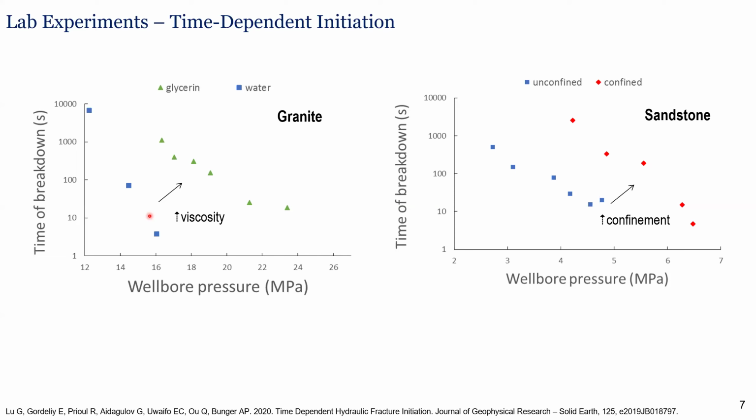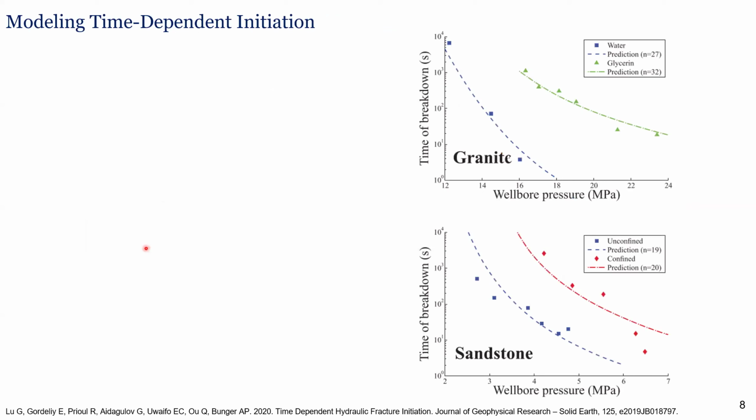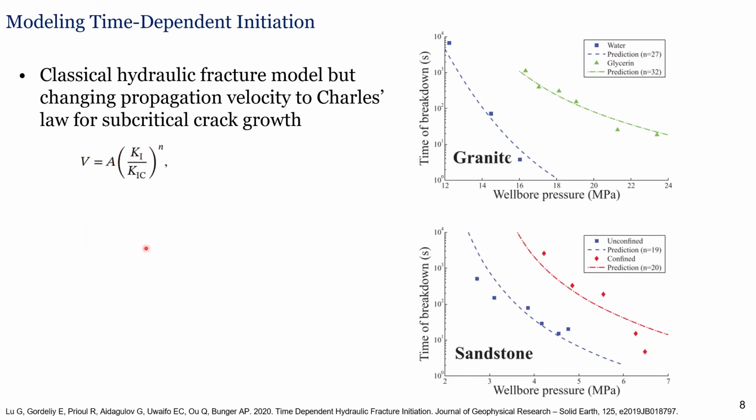That's not what we see here. We see time dependence over a wide range of time scales, and that is not consistent with what we can model using diffusion. What we ended up having to do was actually change our propagation condition to recognize that the propagation condition embedded in our hydraulic fracture model, which said that K1 fracture, the stress intensity factor,